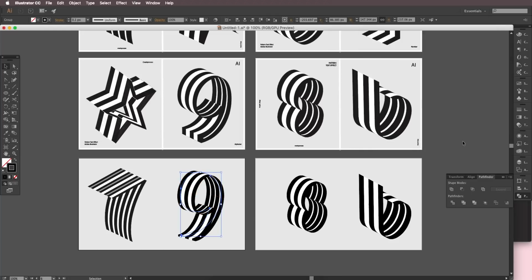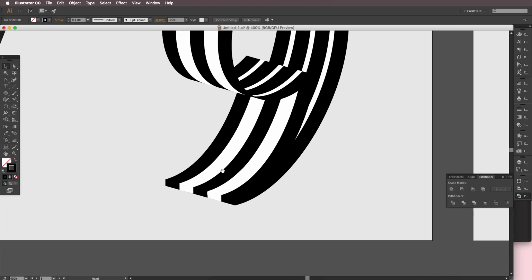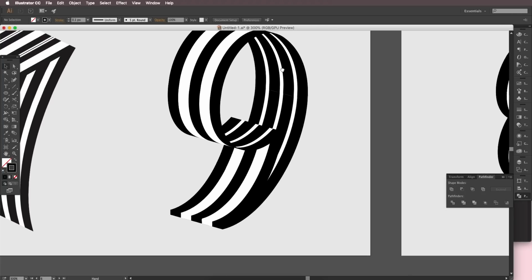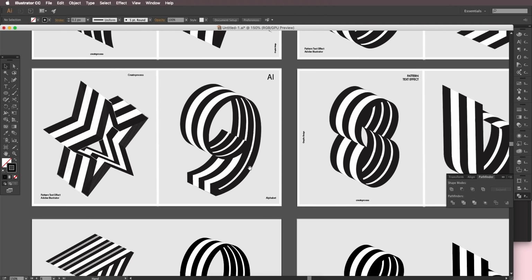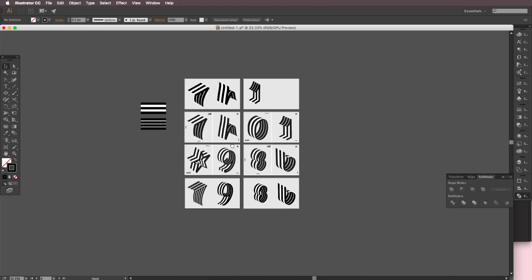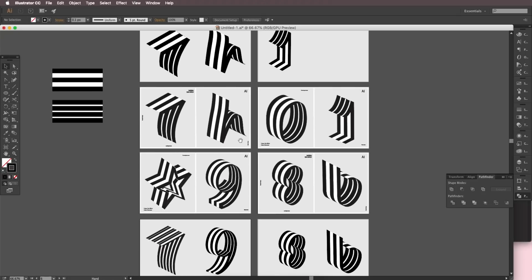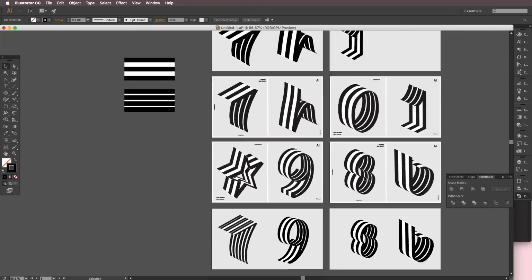And if I check it out now, wow, it's done exactly perfectly. So all the lines are aligned perfectly. The inner surface has that interesting design, and this one. So this is the first way where you can use the symbol, and you have created that custom design, use the symbol and apply the 3D Extrude and Bevel option to create this amazing text effect.